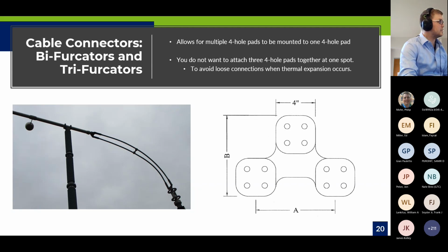Another thing I'd like to note is you never want to lay more than 2 4-hole pads or 2-hole pads on top of each other. Going back to thermal expansion and the vibrations due to the 60 hertz, that will start to shear and chip away at both the top and the bottom connection to the middle 4-hole pad, and pretty steadily increase the resistivity that we don't want there, and those air gaps won't help.